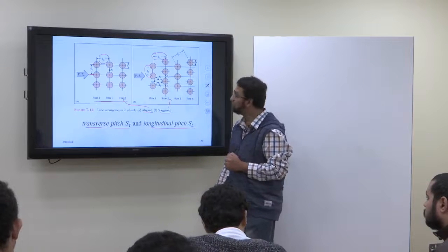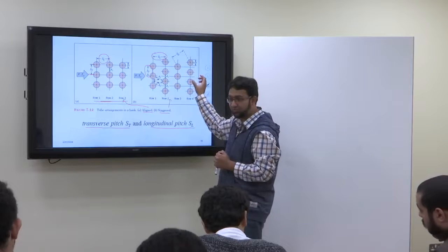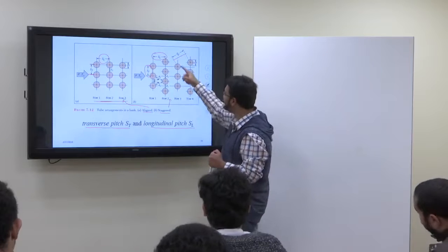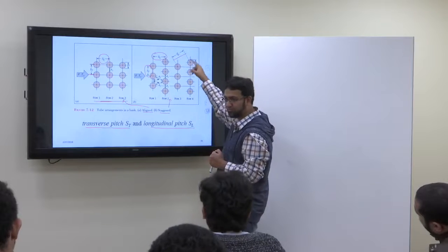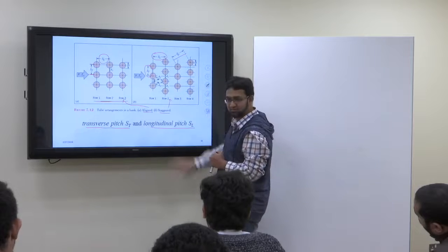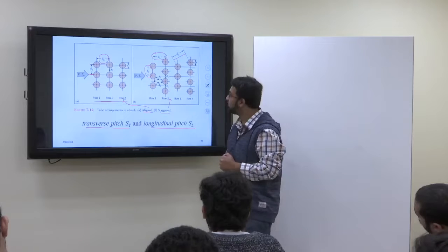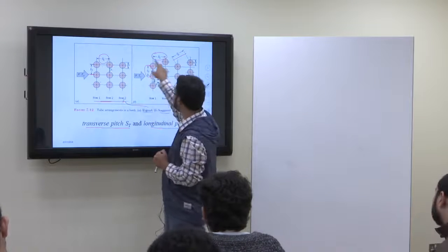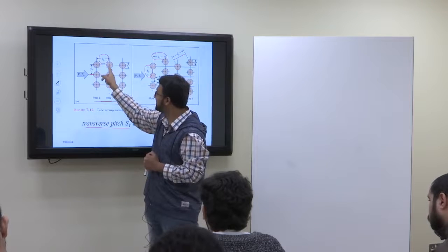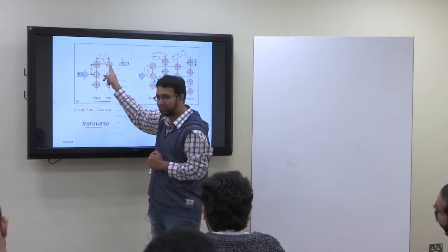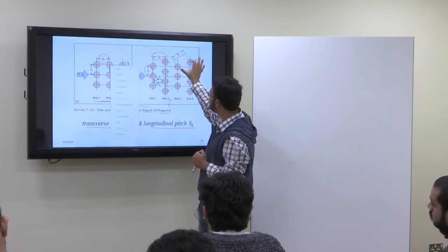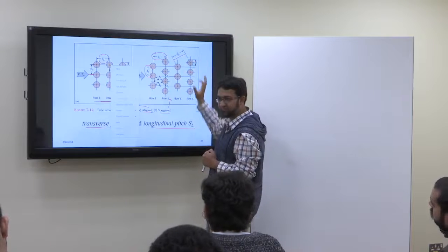Okay. And then for the transverse arrangement, for the staggered arrangement, we also have another distance, which is SD. SD is the center to center distance between two tubes in different rows. In the aligned case, SL will be this thing, SD will also be this thing. But in this case, SL is this thing, but SD will be a little larger than SL.